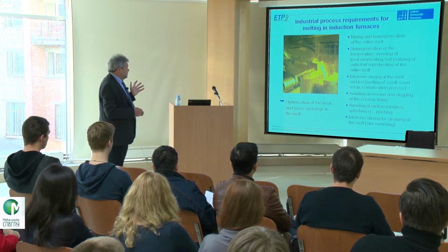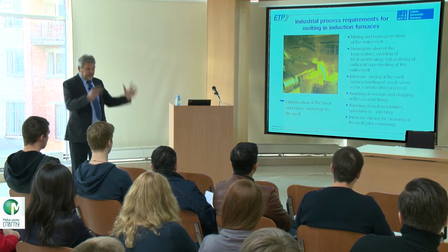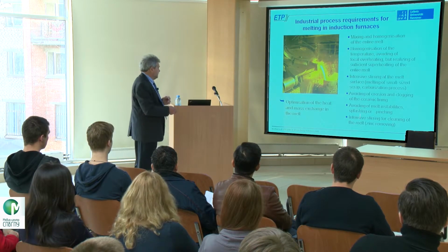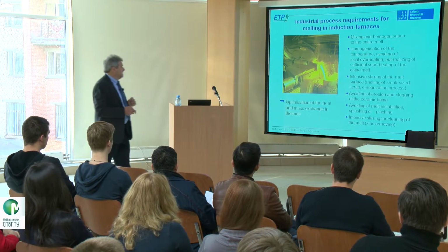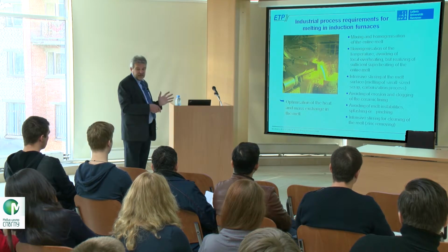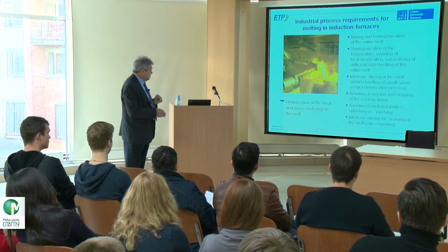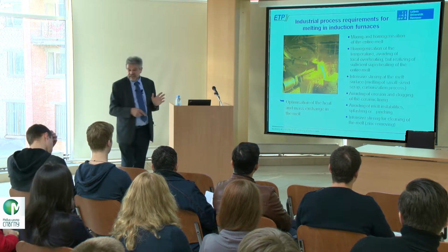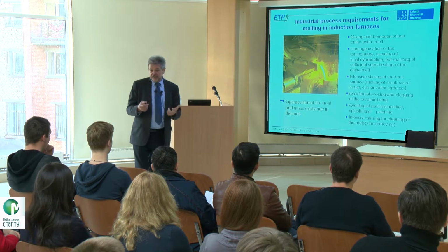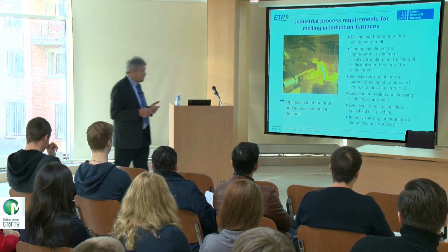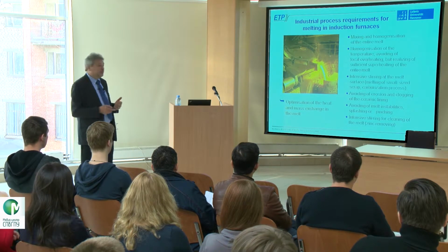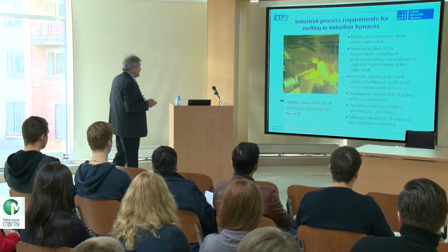We should also avoid melt instabilities, that the melt, being a liquid, comes out due to forces, splashing or pinching, as we call it. And sometimes we need extensive stirring for cleaning of the melt. One very current example is removing zinc from steel scrap coming from the car industry, because the car industry uses zinc, and zinc has to be removed.